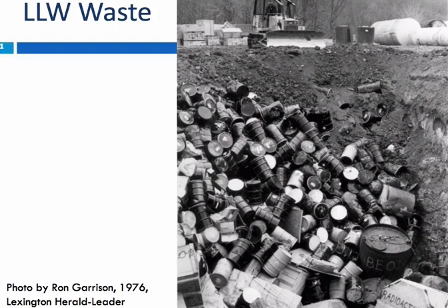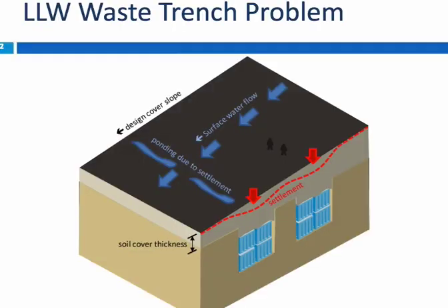The Maxey Flats site took waste from, I believe, more than 60 responsible parties, including the Department of Energy, a number of universities and hospitals and other sources. That included everything from research-derived waste to medical waste and other sources of radioactive waste. And in the interest of limiting people's time of exposure, those wastes will be placed into various containers. Those containers have air in them, and what we're concerned about when we're looking at the final cover is the possibility of those voids later collapsing and causing subsidence at the ground surface.